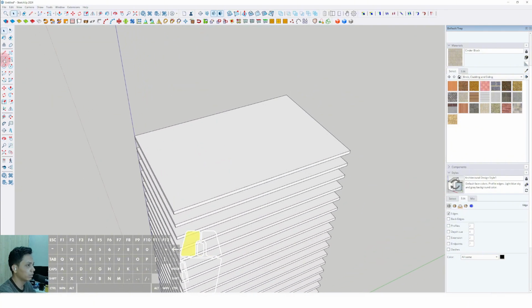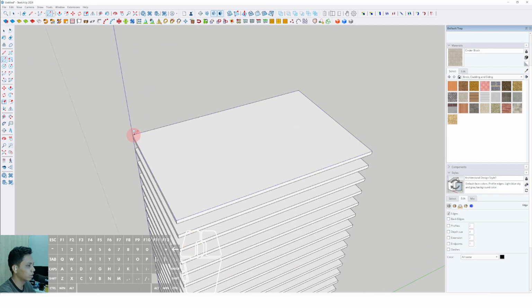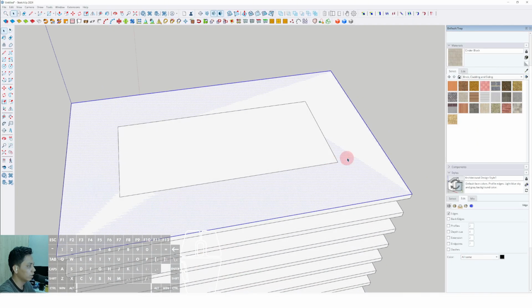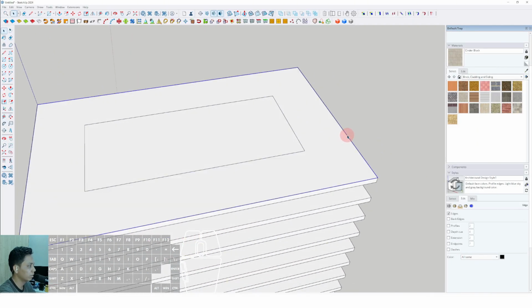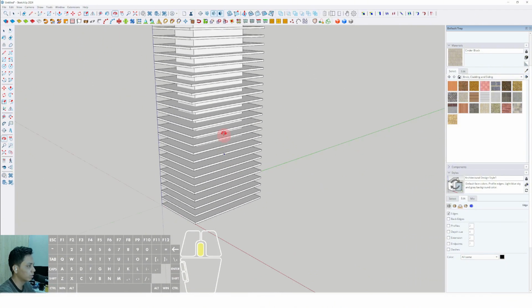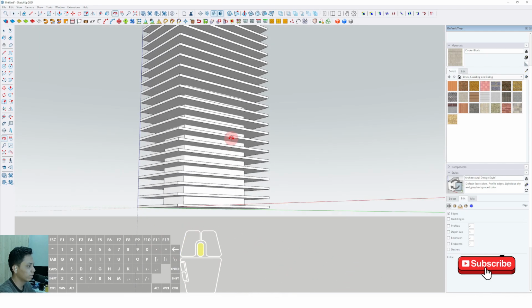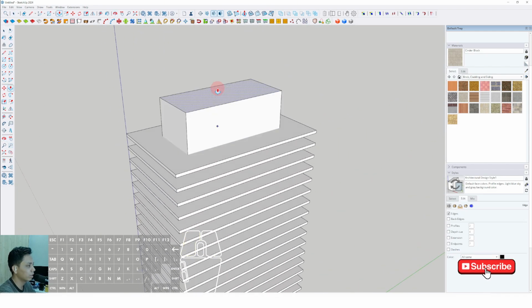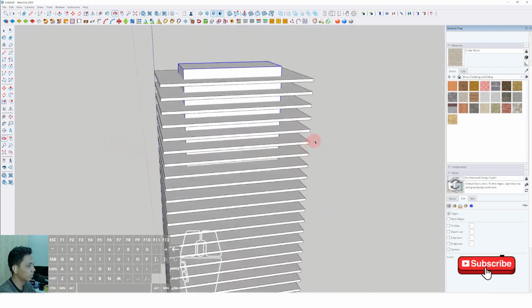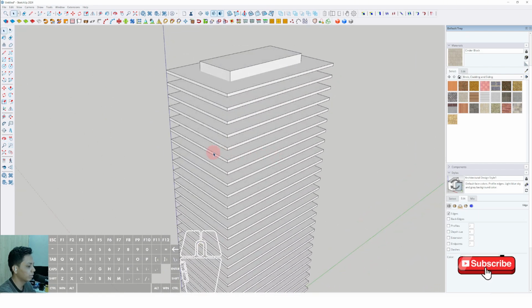make the core building with rectangle. Click from this position until this position, and click this plane, offset inside around 9 meter. Okay, and delete some unnecessary plane. Okay, then click this plane, select push, and place to this lower ground here, and push it up until 3.5 meter. Okay, triple click, right click, and make group, and then we can make the another slab